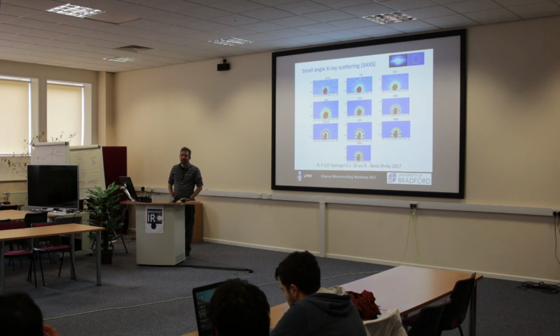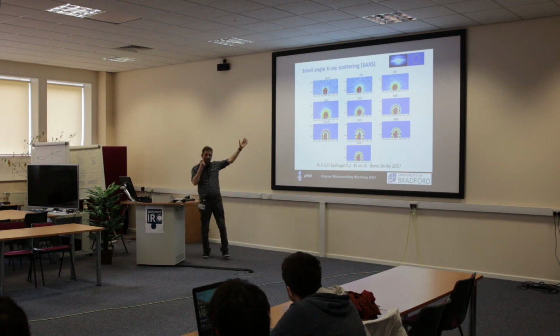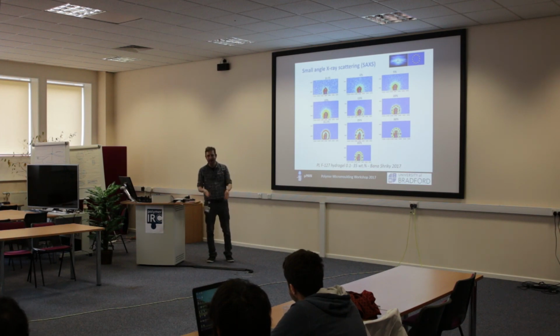How big can a monocrystal be? Oh, you can grow crystals this big, can't you? You can grow massive crystals if you wait long enough, with the right sort of salts. For a polymer, you can get millimetres, certainly. The problem is if you've got one growing, you don't grow one in isolation, there's probably another one growing quite nearby, then they'll coalesce at some stage. So I can't give you a number, it depends upon how big your injection moulder is, I guess. But millimetres, certainly, and probably higher than that.